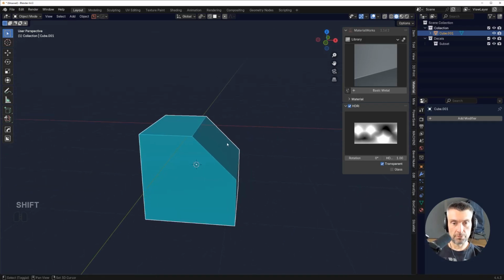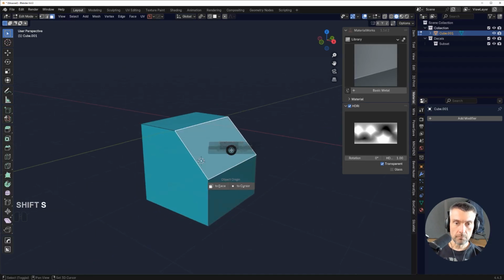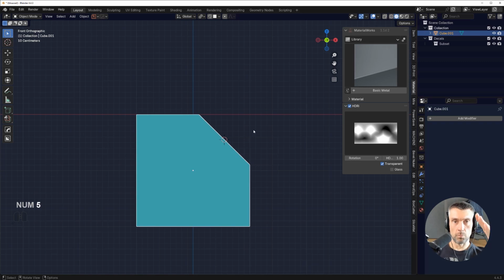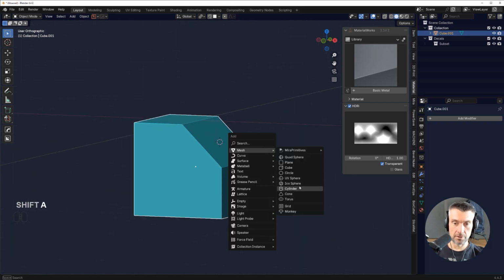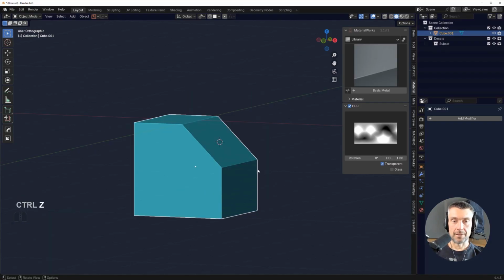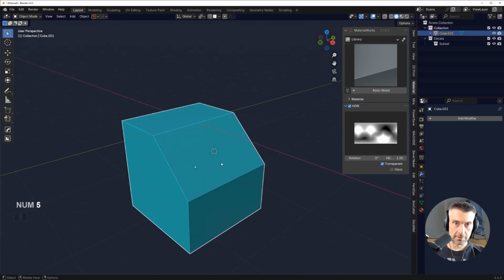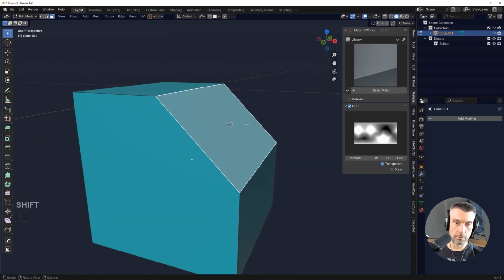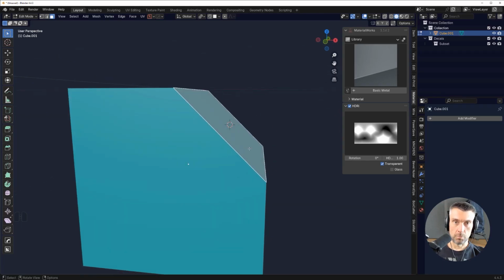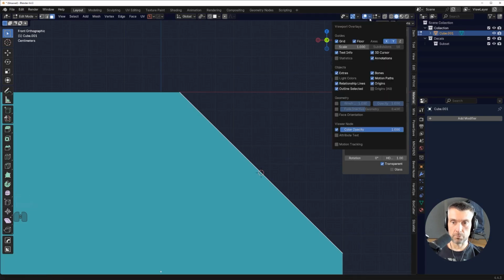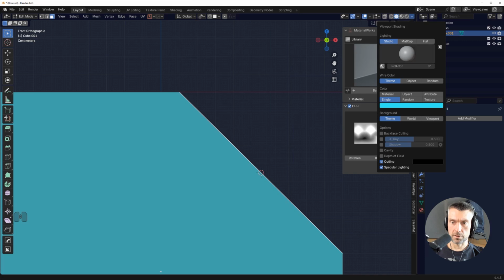You need to move the cursor to the face. The problem is, if you move the cursor to the face using traditional vanilla tools, the cursor will not inherit the rotation of that face, the normals of that face, right? So if I add a cylinder now, it's going to be facing upwards, not at a 45 degree tilt. Now, what the machine tools by default is doing is aligning the cursor to the selected face. So if this face is rotated, the normals are pointing that way, and it's going to align along the normals. And if you don't know what normals are, they're basically like invisible lines. You can actually make them visible if you want to. Where was this thing? It was somewhere here.